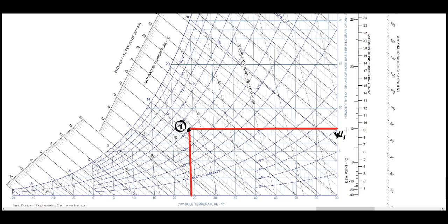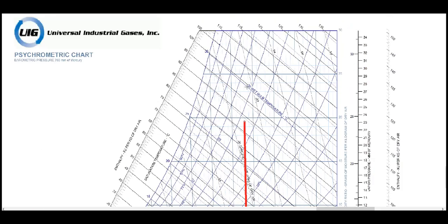Then the second point is to raise it to a 38 degrees Celsius dry bulb. So I'm going to plot the line here again. 35, 36, 37, 38, so this is 38. Going to 37 wet bulb, so intersecting at 37 wet bulb. Okay. So this is 37.